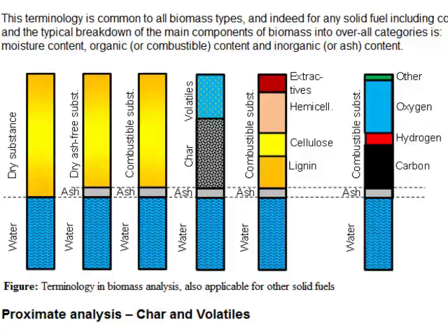And the combustible substance is generally split into two groups, that is char and volatiles, where the volatiles are the gases given off during pyrolysis. Pyrolysis is that we heat up the biomass to 700 degrees without access to air or without access to oxygen, so that we prevent combustion.